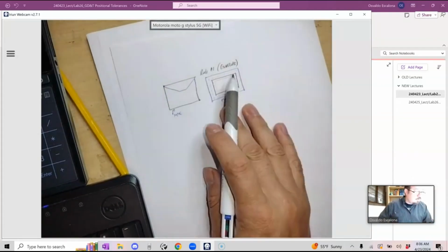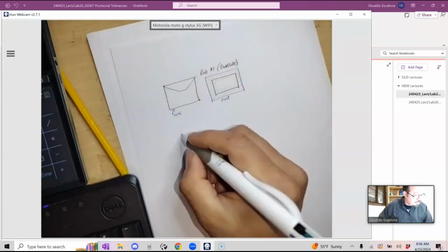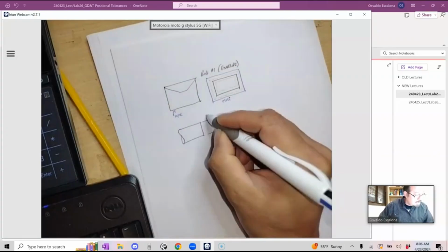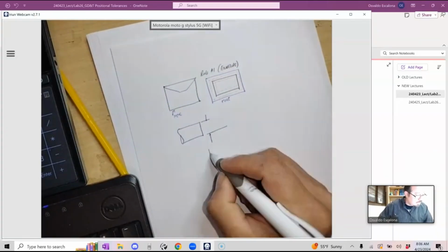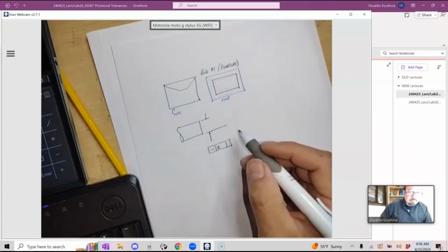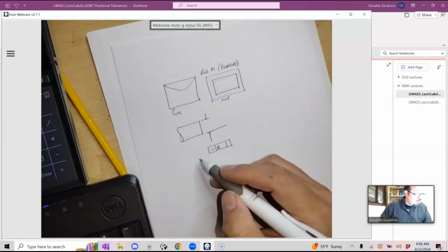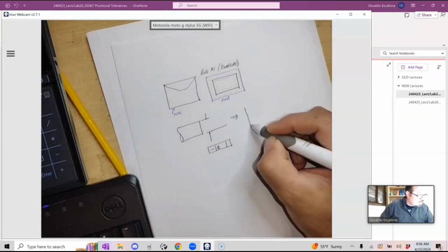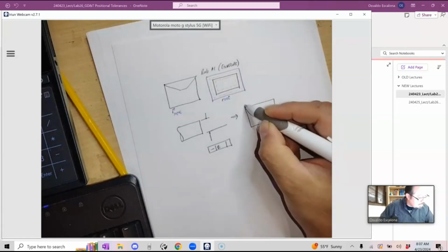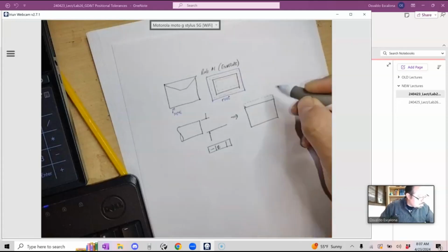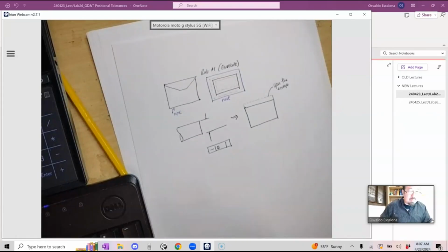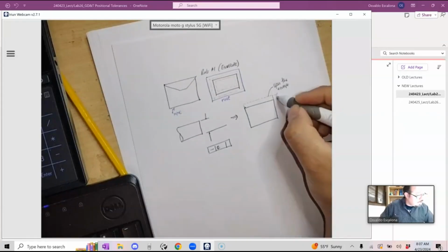I also told you that if I have a feature of size, but now I apply a straightness on the feature of size, then I automatically override rule number 1. Rule number 1 now says, you know what, I'm going to open the envelope and allow you a little bit of variation. That envelope is going to allow you variation in terms of geometry imperfection.